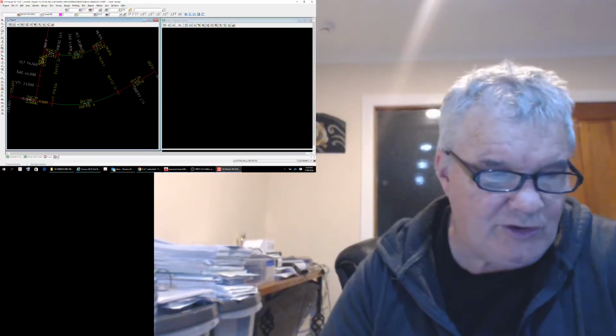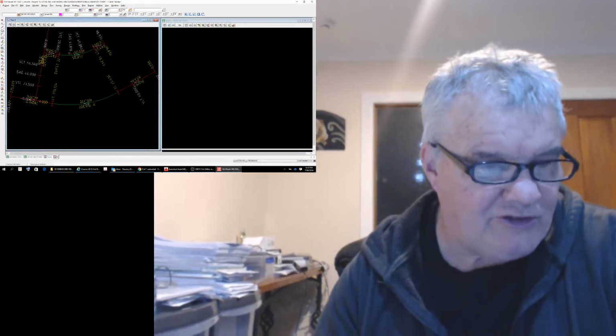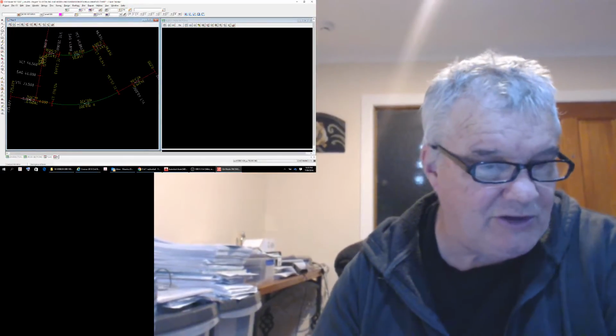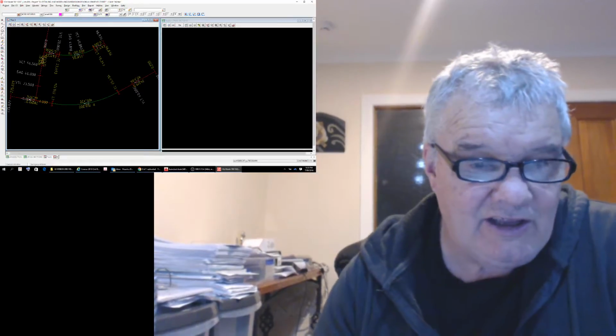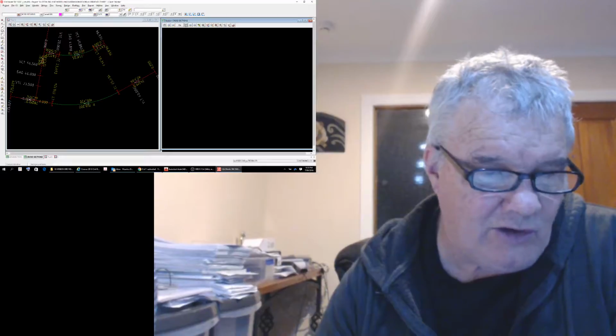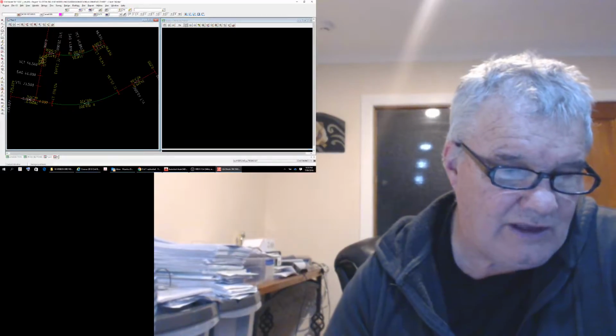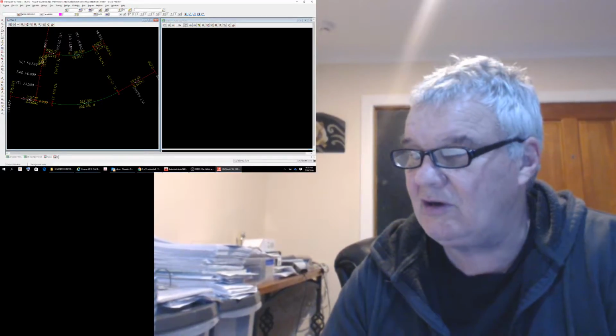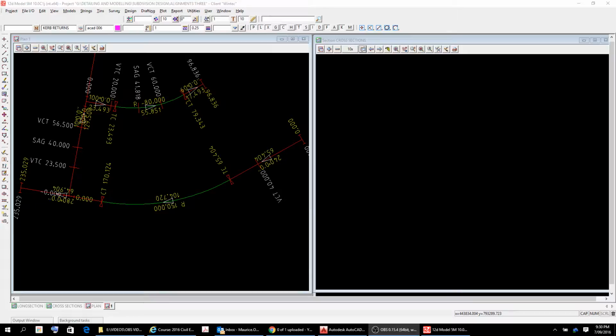So what I need to do is to bring these roads up a bit because we're a bit too low in these spots here. So first of all, I'm just going to grab this alignment here and get it up into the big picture, just so you can see what I'm doing.